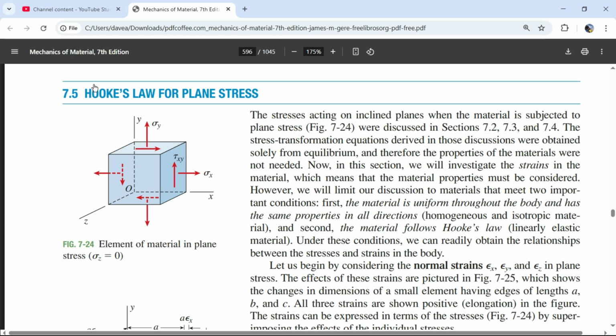So we have a force over here on this bar. We cut it perfectly perpendicular. We know we're going to have stresses that are associated with forces, so we're going to have a normal force and a shear force. But because this is perfectly horizontal, we won't have any shear force. Hence no shear force. Hence if we have biaxial stress, this will be 0. So then this term would be 0 at any location when we just take the simplest thing of just pulling on something on both ends.